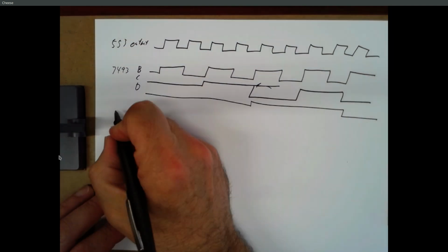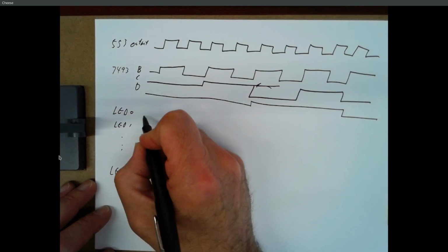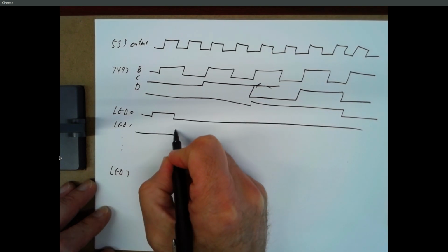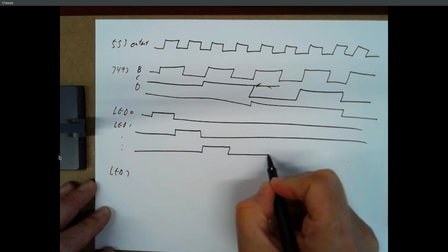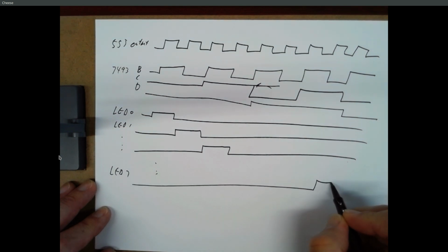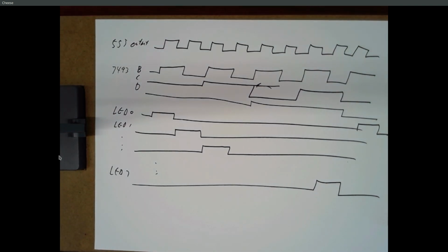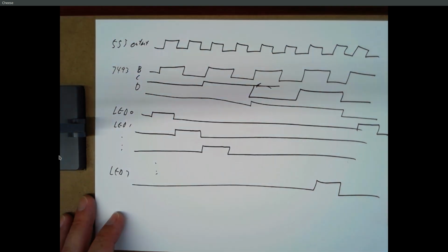And then this goes into your 8 LEDs, and LED 1 turns on for one of these, and then LED 2 turns on, and they do something like this. And then LED 0 repeats. So you want to draw a much neater diagram than I just drew, preferably on graph paper so things are lined up. But basically it shows what the timing is for all the different points in your circuit, right? And it's sort of driven off of the clock, which is coming out of the 555.